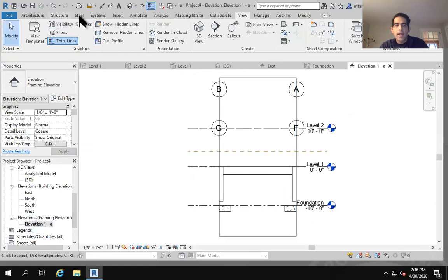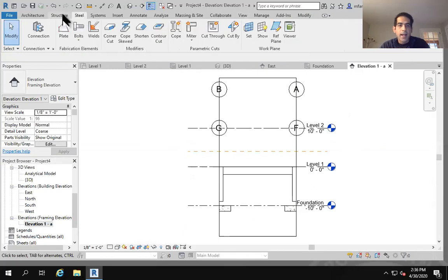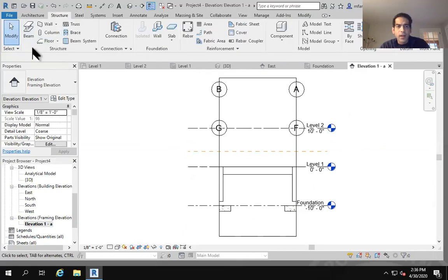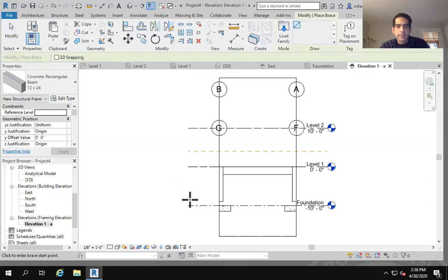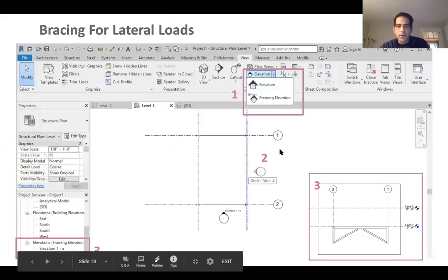And then if I want to add the structure, I can go here and add the bracing. I mean, obviously this is not working for this one because it's concrete, but this is going to be easier to manage where I want to place my bracing. So if it is going to be going halfway or going all the way to this side. For concrete, it's not this way unless you want to create some sort of a cantilever or something, but that's a different story. So assuming that, for example, you have a steel structure, that's the way of doing this part.